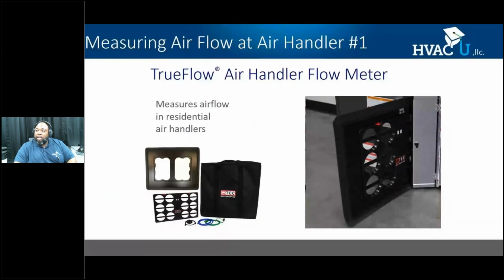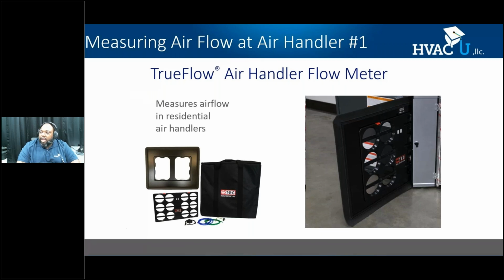All right, our next duct system evaluation tool is measuring airflow. You can measure airflow really quickly with a lot of tools that are on the market these days. This is one of them. You can get static pressure and airflow in about 5 minutes. It is really easy to evaluate duct systems to let you know if you have a duct problem and if they warrant the other testing methods that we talked about. So a really nice tool to have.